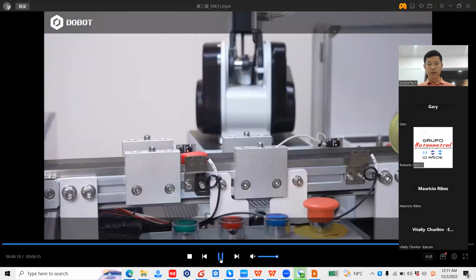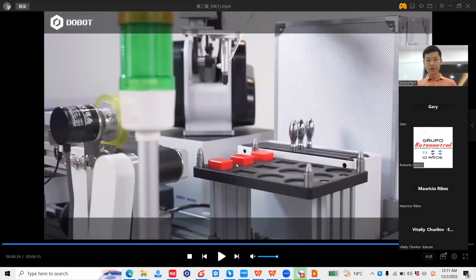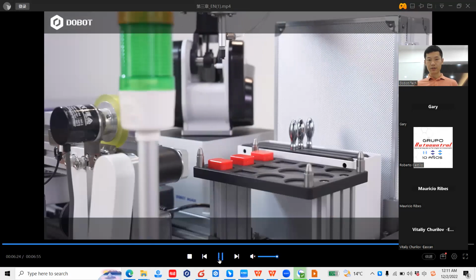So actually you can run this without the camera, but without the camera, you have to make sure this is always in the same direction that you set up. But with the camera, any rotation here, if it's off by 20 degrees, 30 degrees, whatever degree, our vision system can recognize it and rotate and place it at the correct drop-off position.